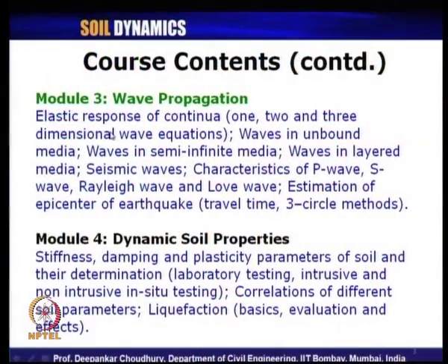Under module 3 our subtopics will be elastic response of continua, 1, 2 and 3 dimensional wave equations, waves in unbound media, waves in semi-infinite media, waves in layered media, seismic waves, characteristics of P wave, S wave, Rayleigh wave and Love wave, and estimation of the epicenter of an earthquake by using different methods like the travel time method, 3 circle method, etc.